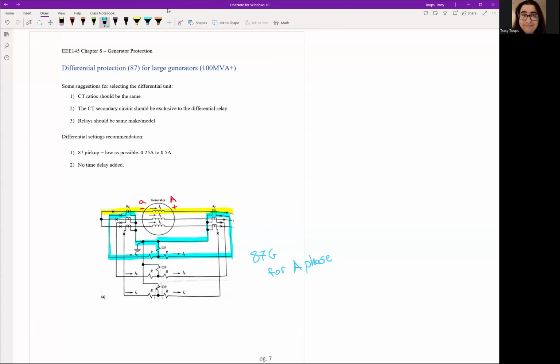Really, they should be the same manufacturer and built from the same assembly plant on the same assembly line. We try and make them what are called sister CTs. Okay, you really want them to come from the same place. That way there's no variation in metal density or workmanship. Okay, because you need these as accurate as possible to be perfect copies of each other.